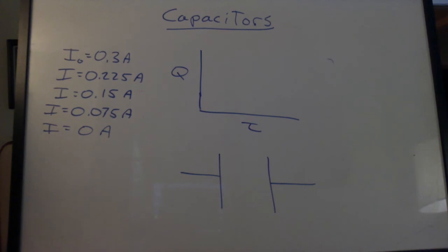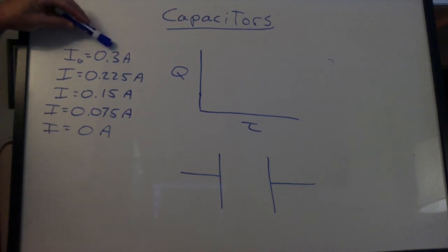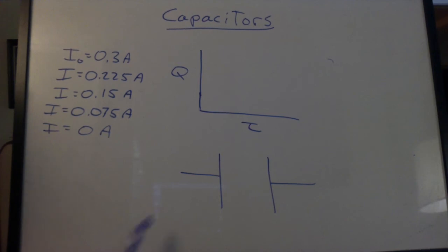We'll draw a different graph to analyze this. This is charge per time, not charge per volt. How much charge will flow onto the capacitor initially? Look at the current. The current is big initially, so the most charge flows on in a short amount of time the moment we close the switch. There's nothing here to repel the incoming charges, so we build up charge quickly.